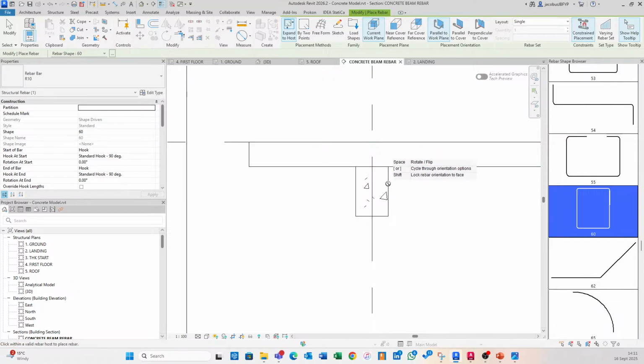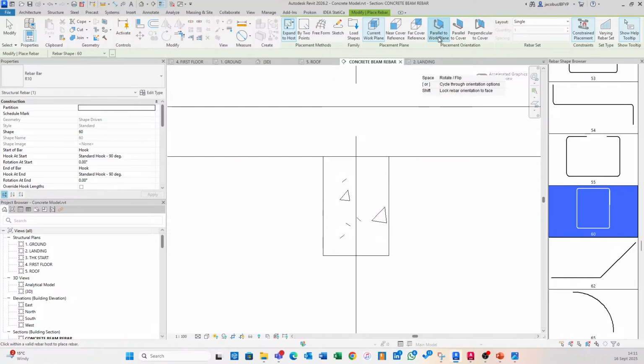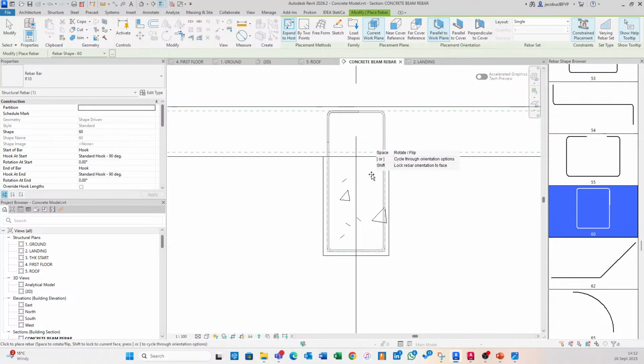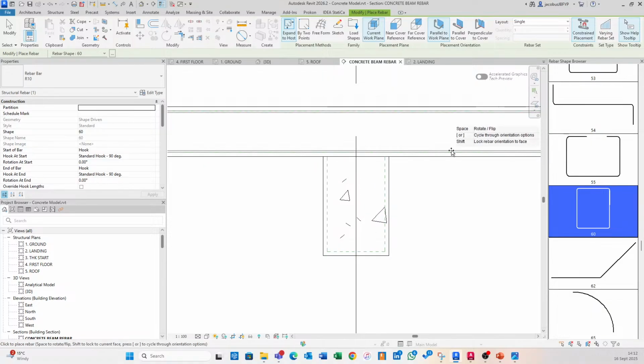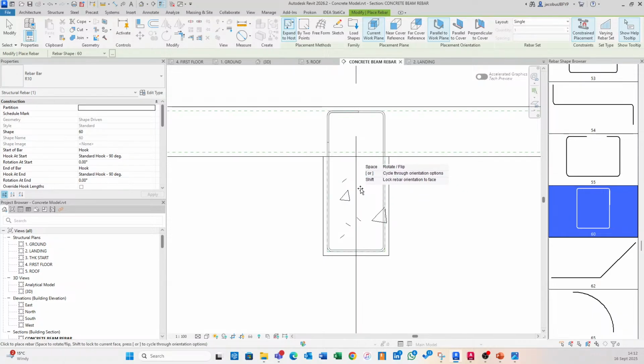When you want to place a rebar element and the way it displays is not quite right, the placement orientation might be the thing to adjust and to look at. Right, so in this case, parallel to work plane is perfect. And you can see in this case where Revit actually sees the slab and the beam as a single host in a sense. Now, that is useful because in general, this would be a portion of the slab and the beam we'd consider then a T-beam, but we might not want to do that.